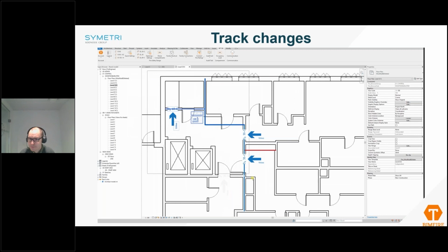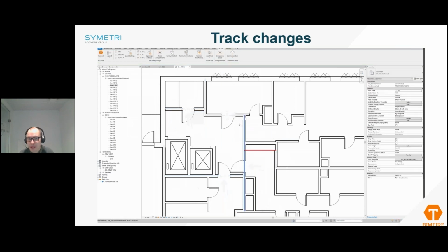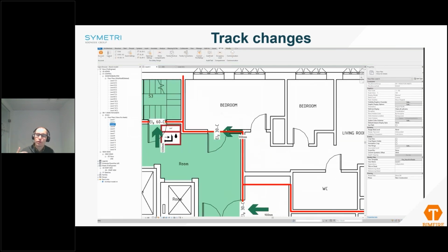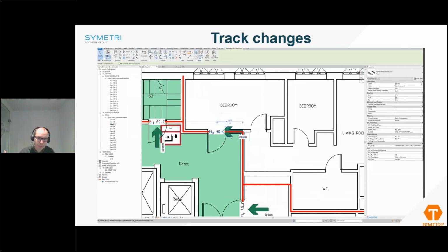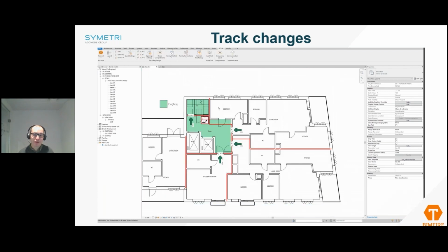But in the end, those walls will be split, because usually it's going to be a shaft wall, for instance. You're going to have a shaft wall and an interior wall, or a bathroom wall. So they're going to change either way in real life. So you can start pushing these a bit forward when you start using your generic models. Just make the shaft walls only shaft walls, and then complement with the interior walls that you're going to change later on. But start with generic, and it's going to follow. It's fine. We can always manually fix these as well.